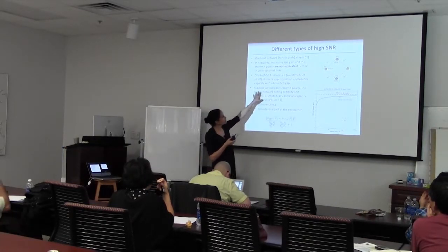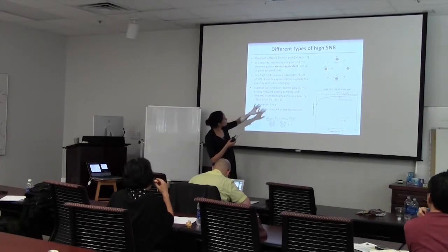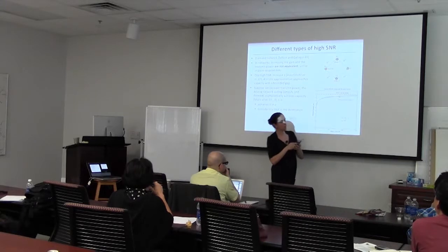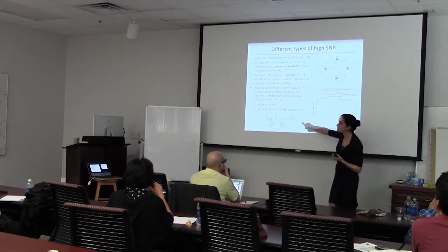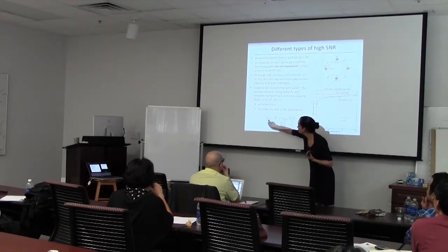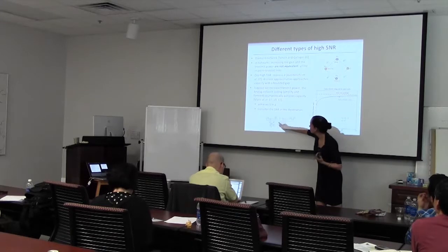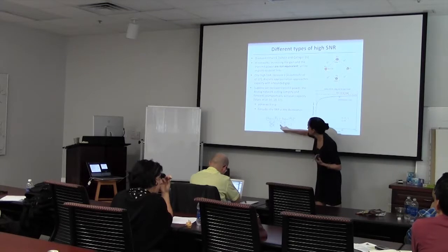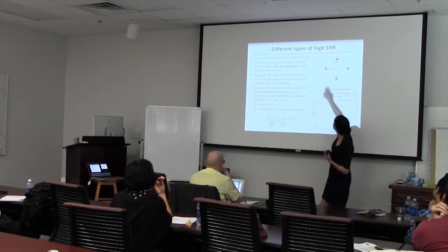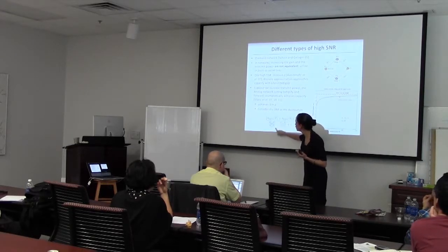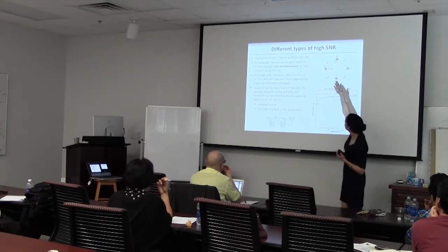So suppose that here instead I increase the transmit power. Then the analog network coding, which is really amplify-forward, is actually going to achieve capacity. For instance, in this case, if you look at what the capacity is, let's look at the SNR at the destination. So the min cut here is at the destination. So I have the gain from relay 1 to destination, the gain from relay 2 to the destination, and then I have the noise that I'm dragging around. This is the unit noise. I'm going to have the unit noise, and then I have the amplification, basically here, of noise from before.